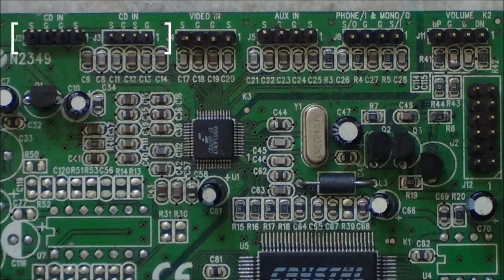These connect to CD-ROM drives' analog output to the audio card using a 4-wire audio cable. Now when you buy CD drives, a lot of the times they come with these analog cables. Now these are usually found on older computers and older CD drives. The CD SPDIF connects to compatible CD drives that have a digital output. Now these look similar to the standard CD audio in, but these only use 2 wires instead of 4.